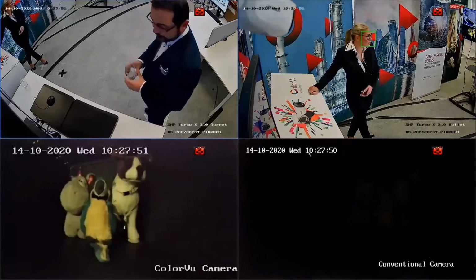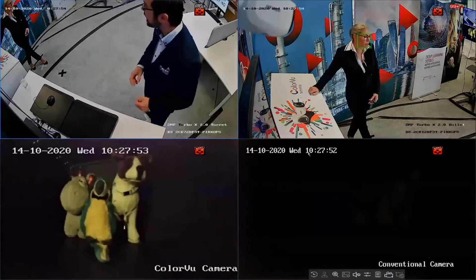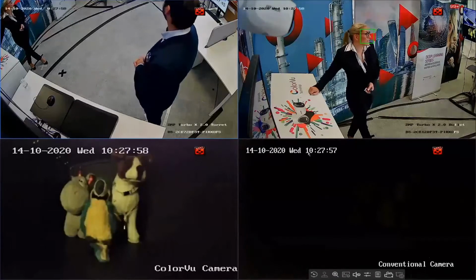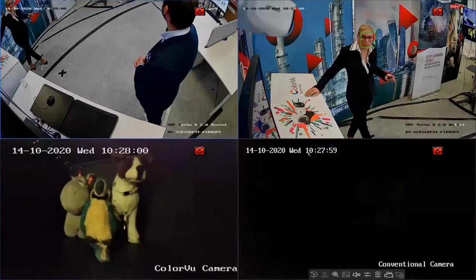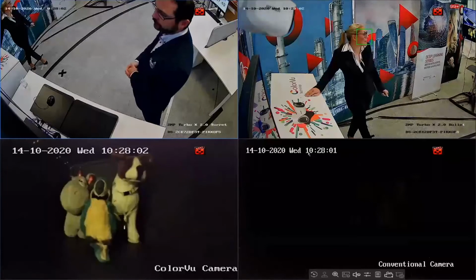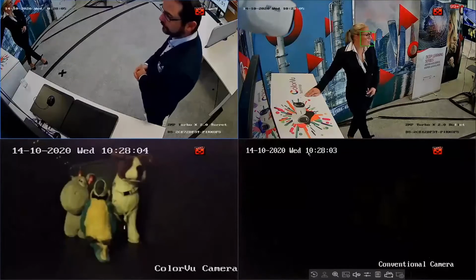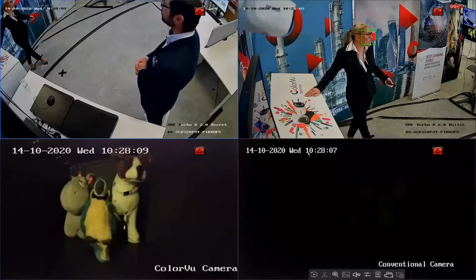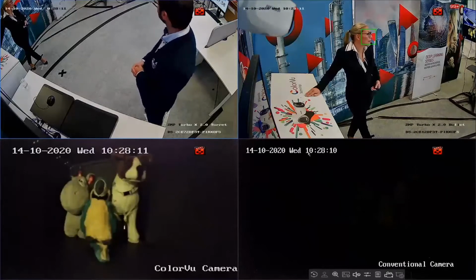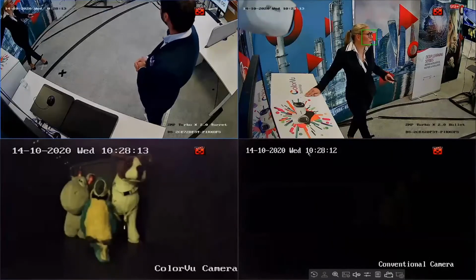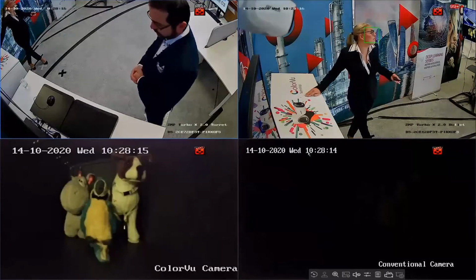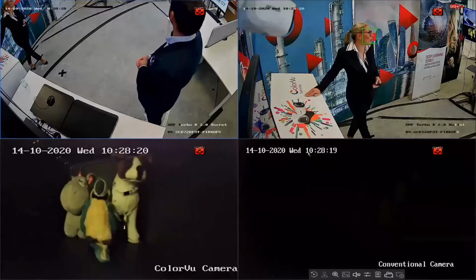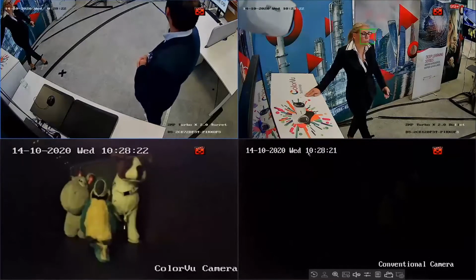It is, if you get in the box, it's quite dark, although I probably wouldn't fit. But the idea here is on the conventional camera, you can see, well, nothing, basically. It's very grainy and it's very hard to see anything. And we get that because the lens is that f1.0 and the lux level is so low. So it just shows you in an environment, you may not actually have the white light coming on. All depends on the lux level in the environment you're installing the camera into and whether it hits that 0.0005 or 3 on the varifocal.